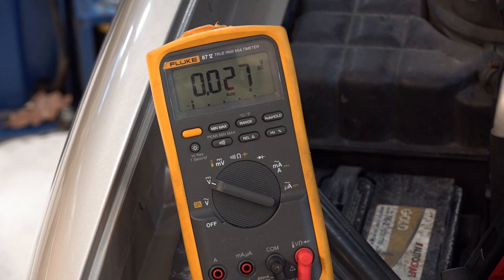Now what I'm seeing here is from time to time this rises and then falls. There we go. Looked like it ran just under 4 amps there, but it was at its peak. Now this is pulsing up and down. So what I'm going to do with this meter, I'm going to do the min-max and actually a peak min-max to see what my maximum values are, and we'll see then what's going on.